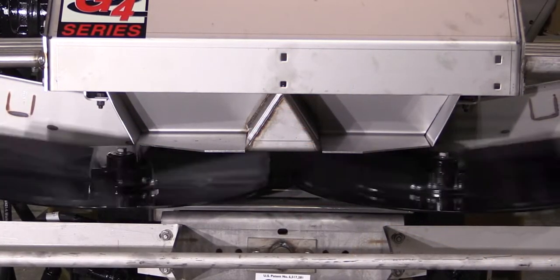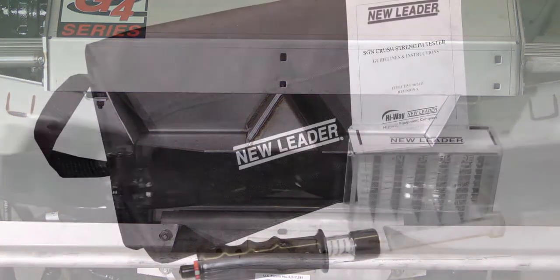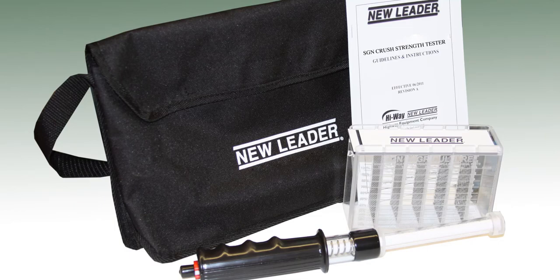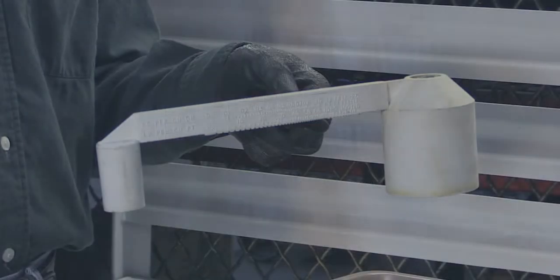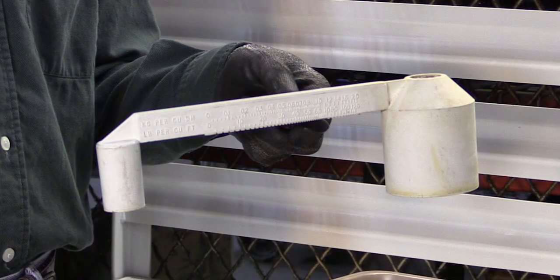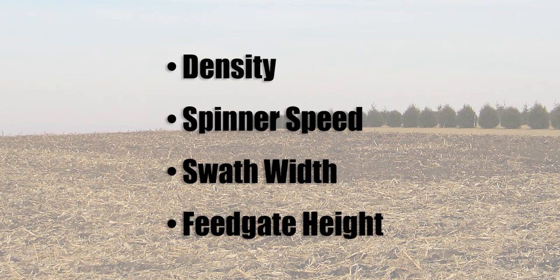Proper spinner speed is very important to obtaining accurate spread patterns. The initial spinner speed setting will be determined based on the results of the material SGN (size, grade, and number) and crush strength test. The SGN, crush strength, and spread pattern test kits are now supplied with most New Leader crop nutrient applicators. Now check your product density to determine material weight. Then verify the in-cab controller has the correct product density, spinner speed, swath width, and feed gate height information.